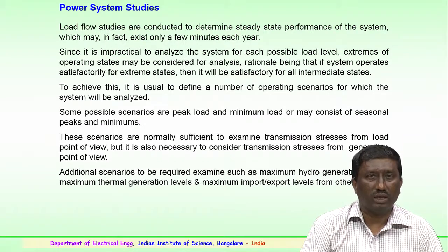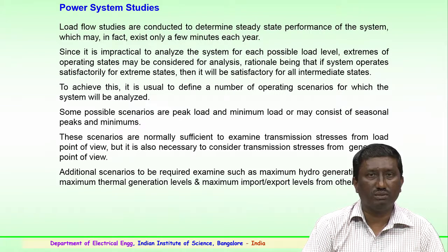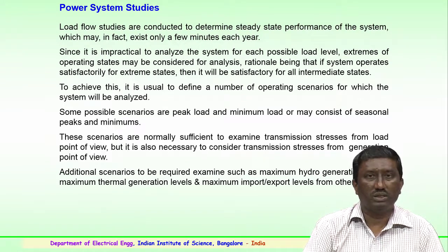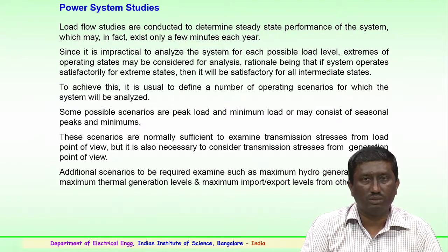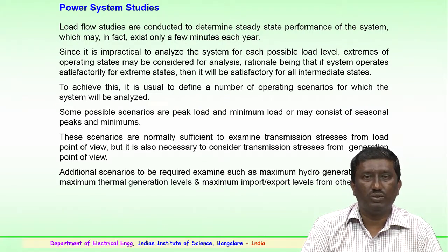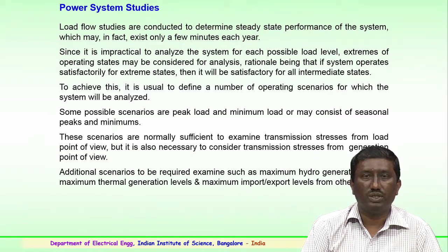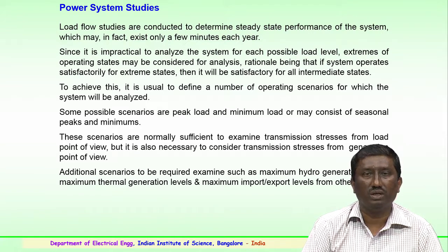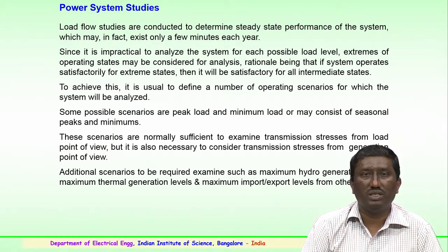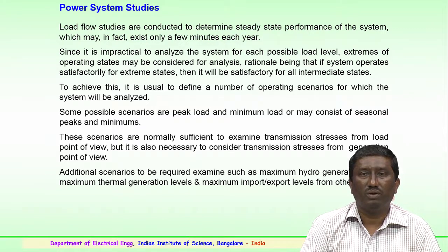So, various studies are being done, like transmission related studies. For a substation also you have to have prior knowledge of the conditions of that area and the voltage level where the substation is planned. Like the power system studies, the important being the load flow studies are usually conducted to determine the steady state performance of a system, which may in fact exist only for a few minutes in a year. So, this is very important, since it is impractical to analyze the system for each possible load level.